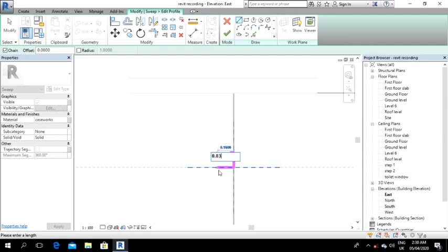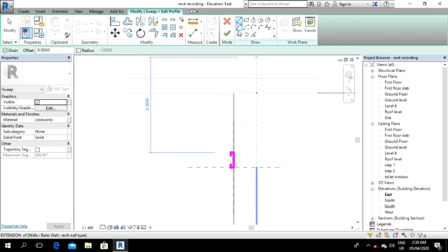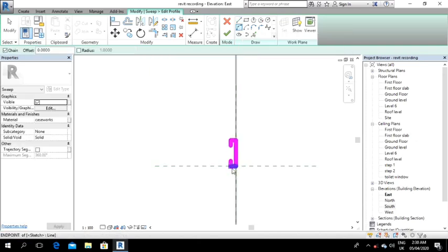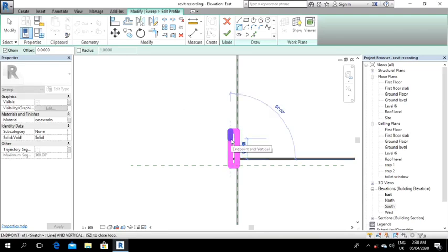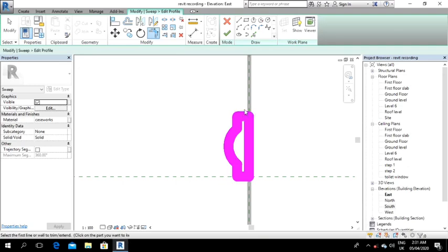0.03, enter, go up a little. 0.03, enter, escape. Now you have to select the angle, the type of arc we need for it. We're using the 3-point method, so click on this arc, click on this place, and then get the arc radius. Let's leave it at 0.056. All right, now our part is set, our section is set.